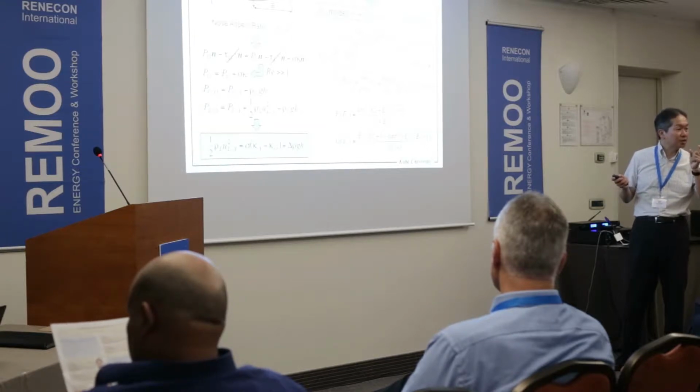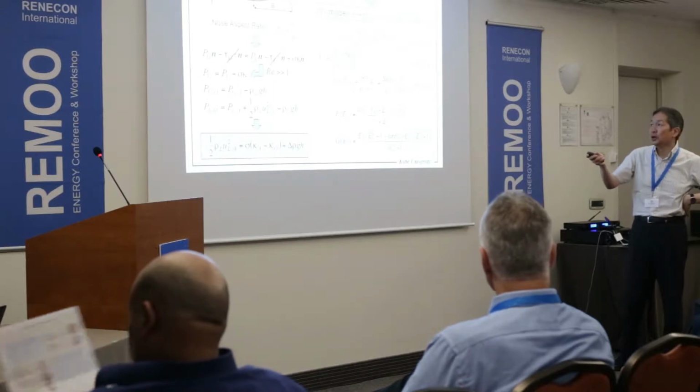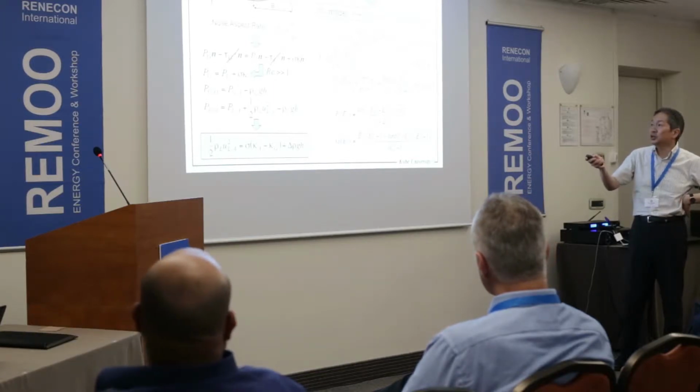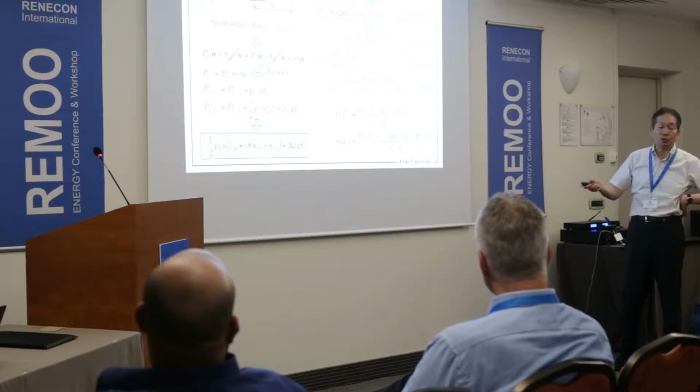So you can apply the potential flow theory because there's no boundary layer formed at the nose of the bubble. Then you can simplify this momentum jump condition into a Laplace equation, and you can evaluate the pressure inside the gas and outside in the liquid by using the Bernoulli equation.